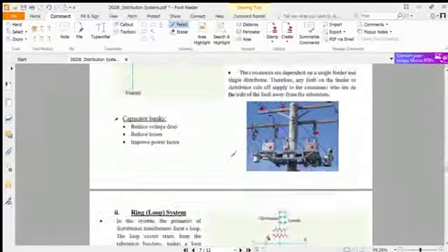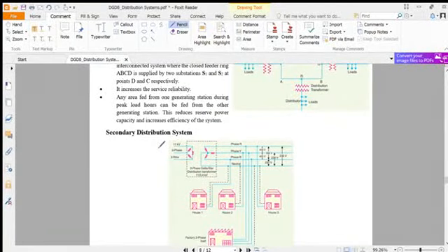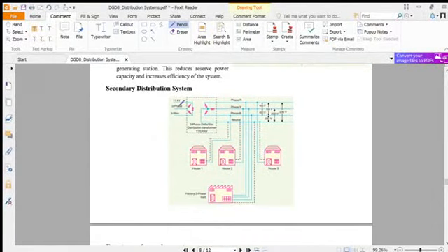And then this is for the secondary system. We see this is the 11 kilovolt line, it's delta connected, whatever the connection, and then it goes to 400 volt. It's a line voltage, so it's three phase. It's red, yellow, blue, and the neutral. The neutral color may be black. It's a black one. And you see, this is the line to neutral voltage, 230, and